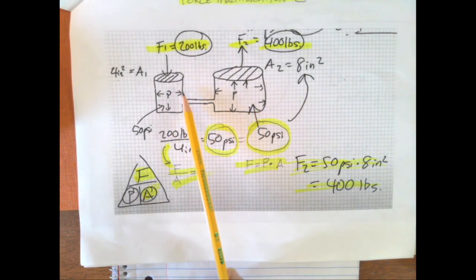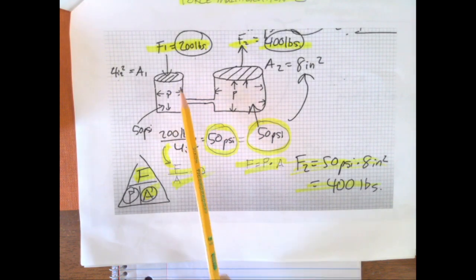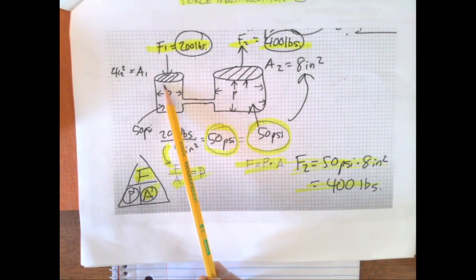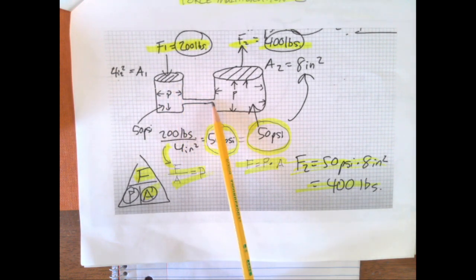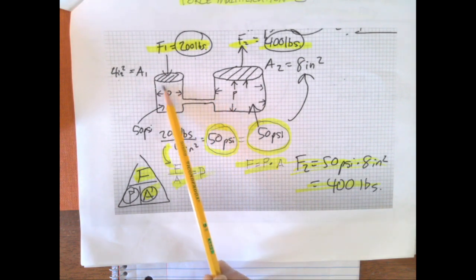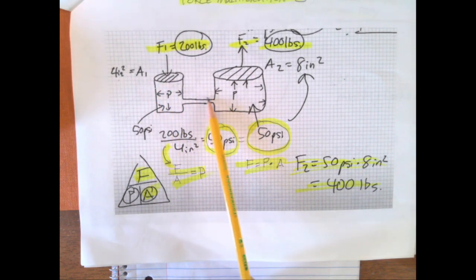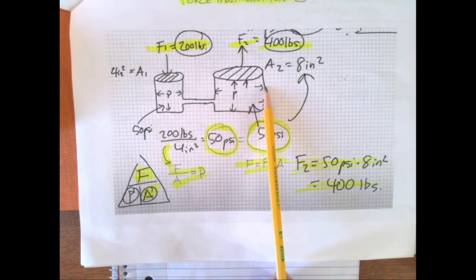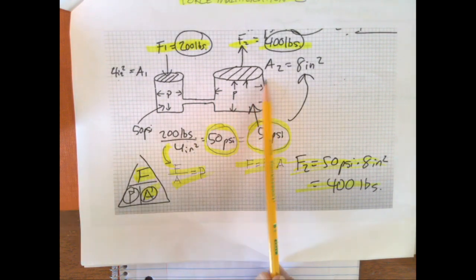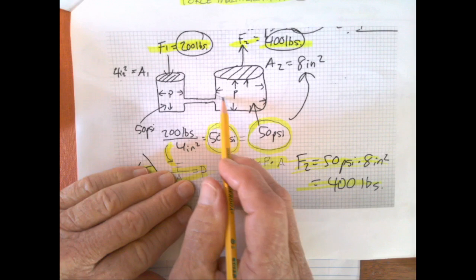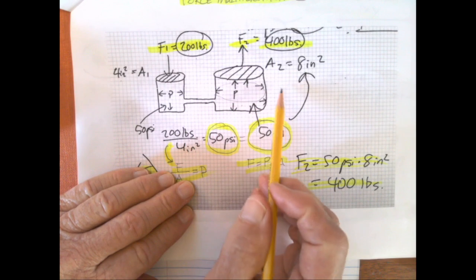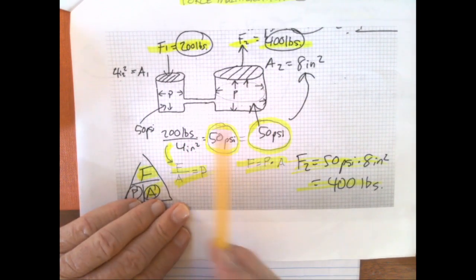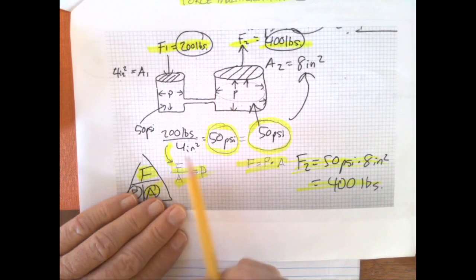But you definitely, your volume, just while I'm here, you gotta push this liquid down, and the volume never changes. But when you push down here, you may push down 6 inches here, but you're only going to get 3 inches of lift out of this piston because the volume is bigger here. Up here, it takes a whole lot more fluid to move a lot less distance. And again, you got a 2-to-1 factor.